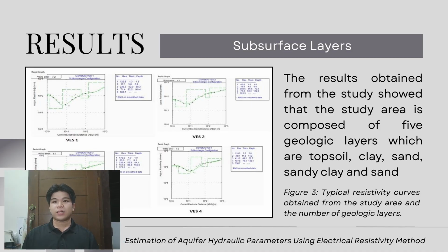The third layer has resistivity of 126.4 ohm meters to 516.7 ohm meters, with a thickness of 38.77 meters to 71 meters, is sand deformation and the first aquifer. The fourth layer is sandy clay. It has thickness of 50.3 meters to 96.4 meters. Layer thicknesses indicate Damaturu's location on the Chad Basin fringe, with increasing thickness towards Maiduguri. The second aquifer's depth precluded thickness determination.